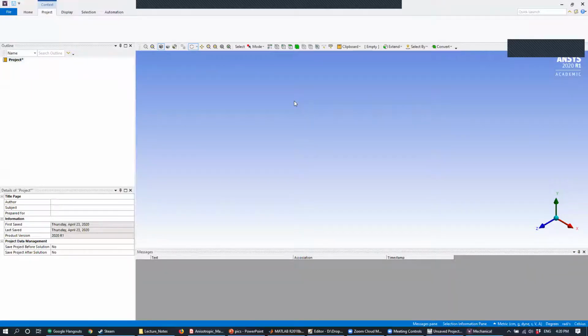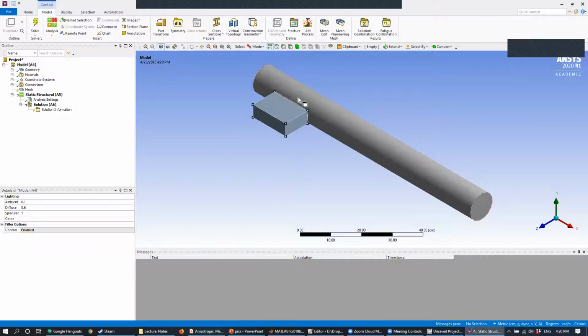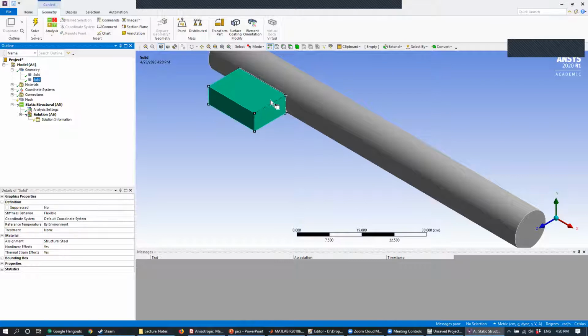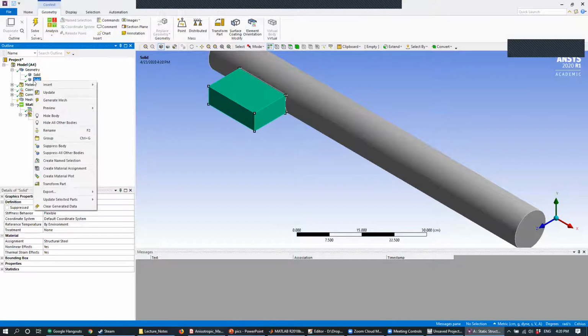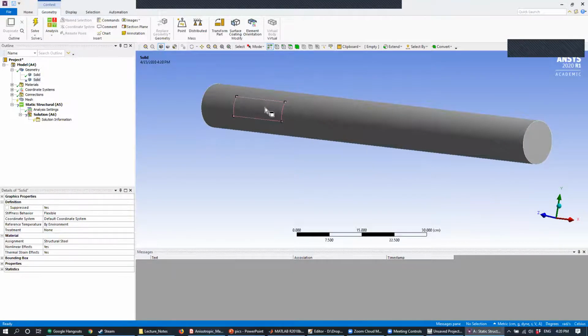Loading, loading, loading. Okay, so you can see we've loaded into Ansys Mechanical. So you can see we have our original cylinder, and we also have our frozen surface here. So obviously we don't want to model that, so we can suppress it. So basically, any frozen surface you can just suppress it. So you can right-click it and click suppress. Okay. So you can see that that solid's gone, but our projection is still here.